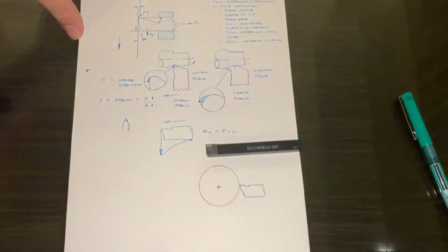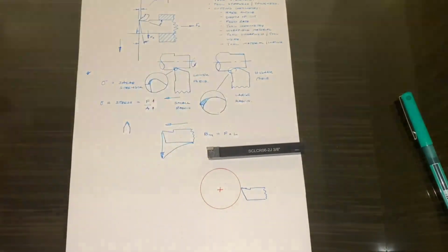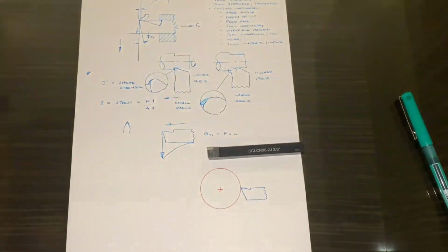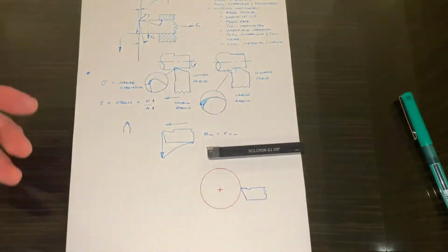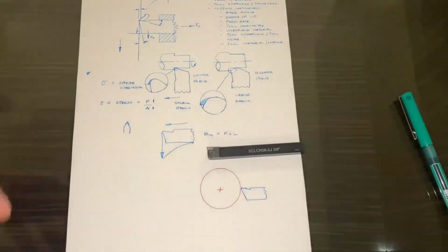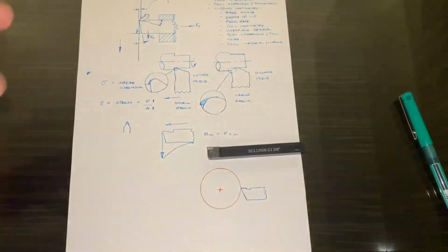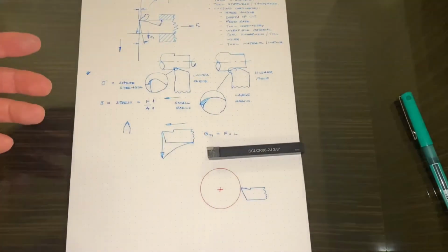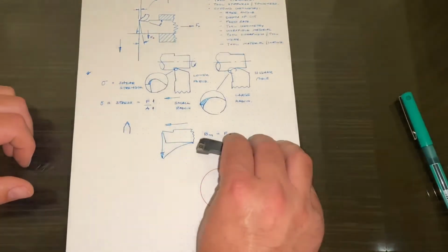So those are some of the principles to be aware of, and that's why sometimes we might not get the kind of finish we were expecting. We might not have the sort of machining efficiency that we were expecting, and we might go back and double check tool height and find nothing wrong, when in actual fact another reason for this could be that we've got the wrong combination of tool geometry for that particular material.